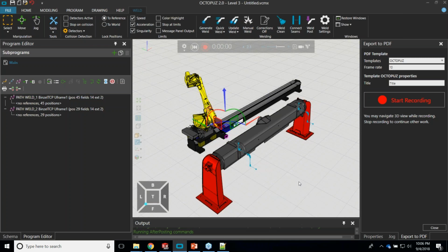When you teach TCP on your robot, our engineers ask that you have an error that's less than 0.6, if possible. I'm not a programmer, but my first time out trying to teach a TCP, I realized very quickly that under 0.6 is difficult to do. But it's difficult to do for a reason.